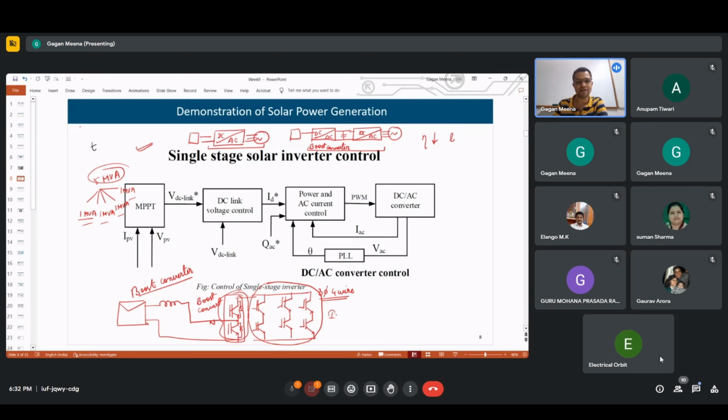All of the three. Then next, select the correct option for DC link capacitor voltage. Which one is correct? That DC link capacitor voltage should be rated less than the peak grid voltage, equal, more than, or doesn't matter. It should be more than the peak grid voltage. Then only there can be power transfer from DC to AC side.